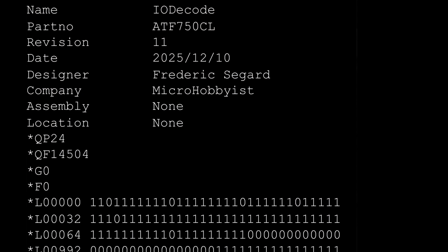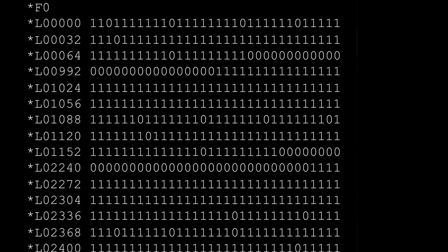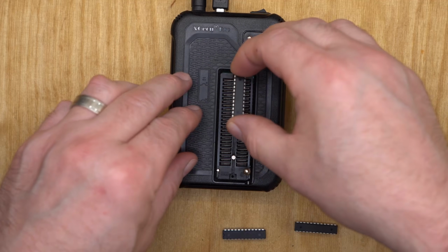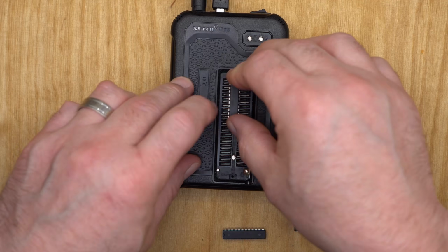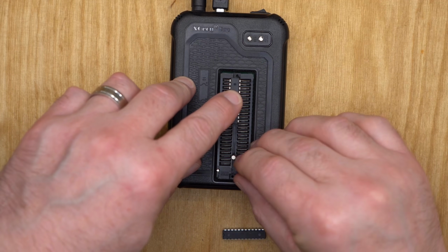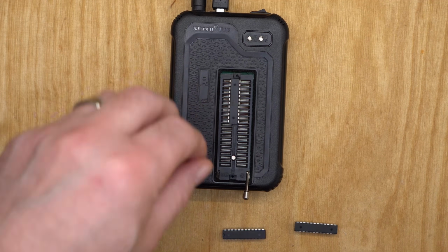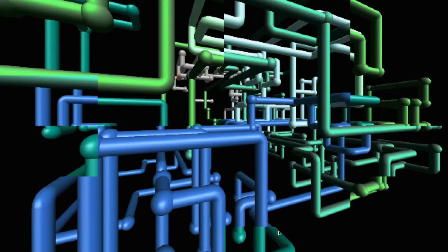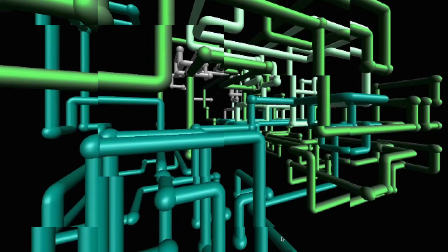The compiler outputs a JED file, which is basically the fuse map for the device. Then you program it. If it works, it's because you told it to. If it misbehaves, you told it to do it too. Just accidentally. WinCUPL, the graphical editor, is vintage. Not the fun kind, more like Windows 98 screensaver crash and took your work with it vintage.